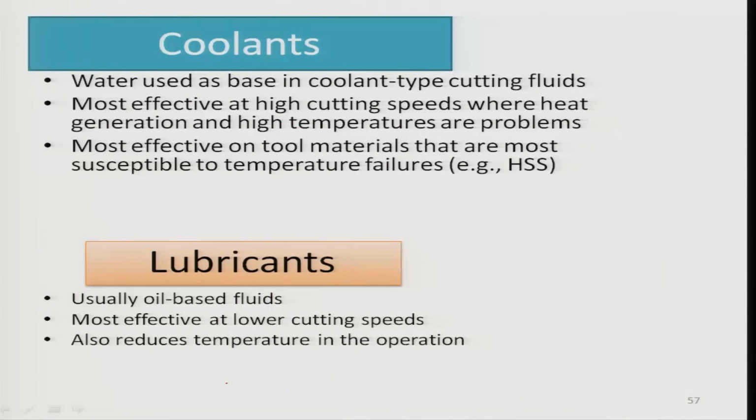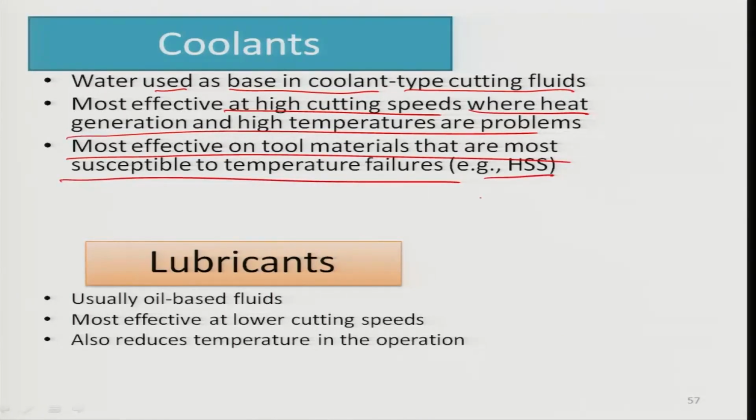If we look at coolants, water is used as a base in the coolant type cutting fluids, and the most effective operation range is at high cutting speeds, where heat generation and high temperatures are very prominent problems. These coolants are most effective on tool materials that are most susceptible to temperature failures, for example, high speed steel, etc.